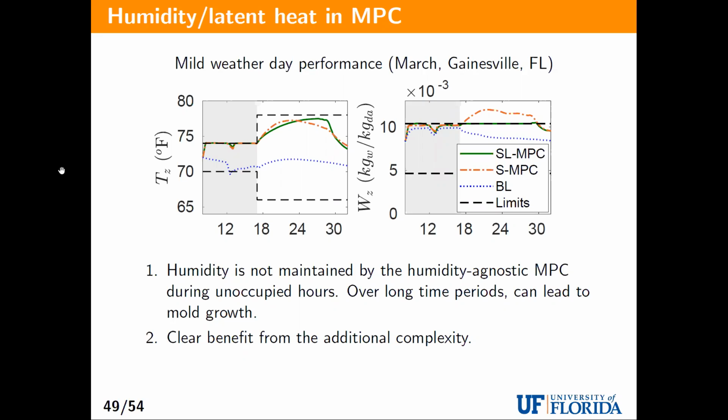Now, of course, you might say, well, who cares? It's at nighttime, nobody's there. But it's almost throughout the entire nighttime. So if it happens for seasons and years on end, you might get things like mold growth and all sorts of other problems. So this actually was kind of useful for us to see that this additional complexity that you have to deal with in designing these controllers, that not only optimize temperature but also humidity, is actually worthwhile in the long run.